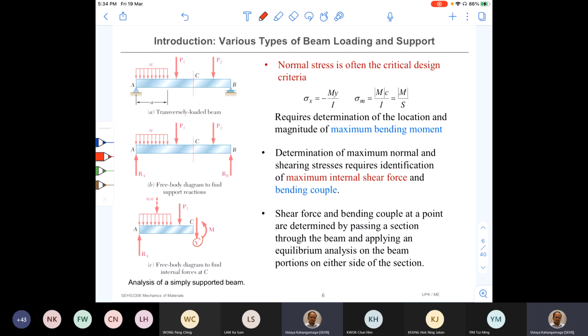We learned in the pure bending case, right? Bending moment creates a linear distribution across the cross section, right? So if you find the neutral axis, we know how the distribution is, something like this, right? Stress in the axial direction, tension or compression, axial stresses or axial forces.